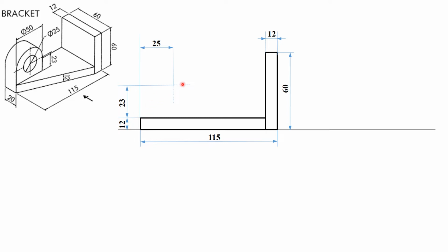With this center, you first draw this curved surface. Look here at the curved surface. Till this point, it is vertical. Both the faces are vertical. After this point, it makes a semicircle which is 50 mm in diameter. This height will be 25. If you add up 25 plus 23 plus 12, it comes to 60. So the total will be 60.